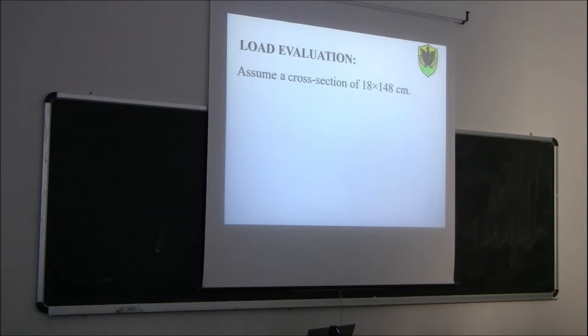So in this case, of course, we decided to use glue laminated timber, and the result of the preliminary design is a beam which is 18 centimeters wide and 1.5 meters high, more or less. So it's quite a big beam, I would say.